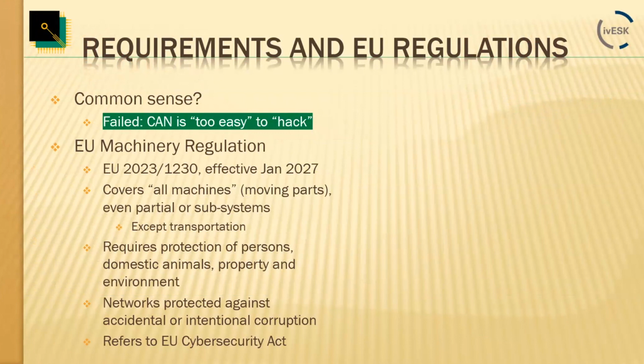Well, for a long time, we tried to get along here without regulations and ask for common sense. However, if you followed a little bit the news on what is hackable all around CAN and CAN-based systems, then the common sense solution really didn't work out. Simply put, CAN is just too easy to hack because, well, the downside of a standard is that you immediately know what you have to transmit to where to trigger a certain action. The better a system is documented and standardized, the more easy it is to manipulate or start injections.